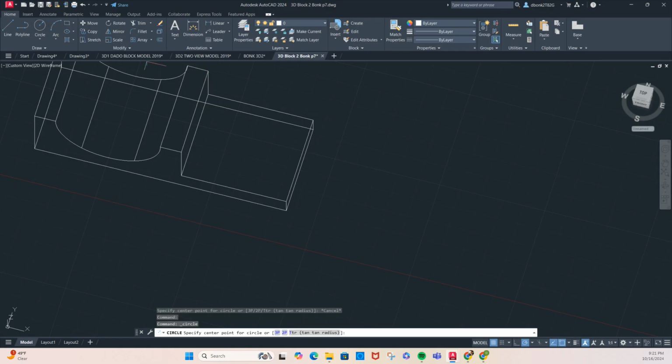So you click the circle tool, go over that surface, find the midpoint of it, and then it's going to do an extension. You're going to tell it to be 3/4 inch away from that edge first by typing in. You got to have those green indicator lines, and it's got to be laid out just the right way for this to work. So then you're going to type in 3/4, and then it starts putting the circle in there because that's the tool we're using. And then now we're going to tell it to be the size we need it to be, which is 3/8. Enter.